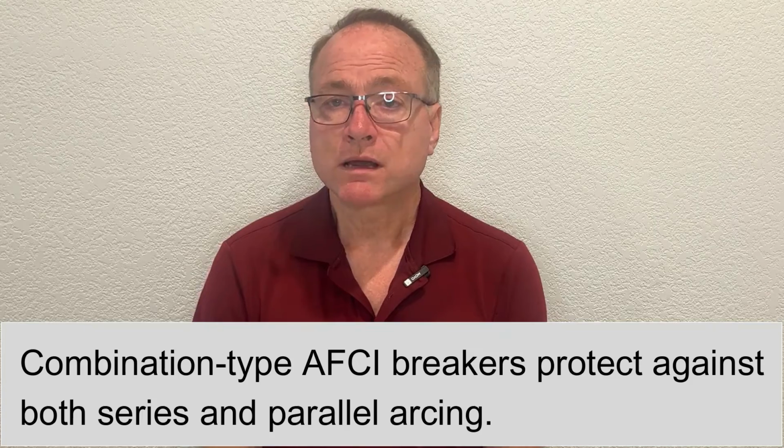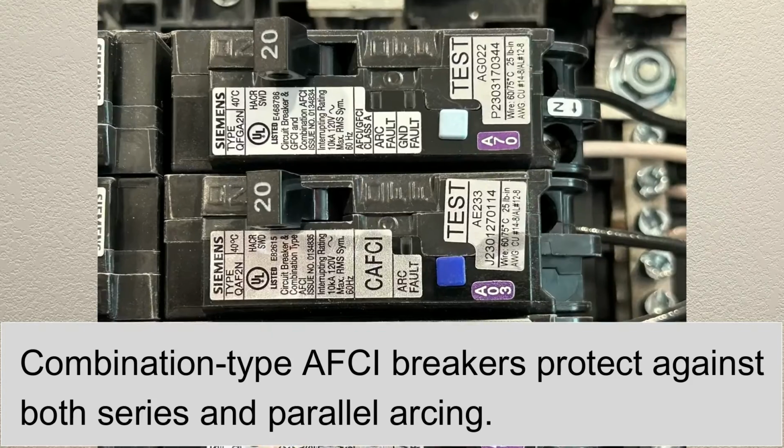When arc fault circuit interrupters first came out in 1999, they only had AFCIs that protected against parallel arcing. But now they also protect against series arcing. So they're much more effective at preventing electrical fires. The type of AFCIs that prevent both parallel and series arcing are called combination type AFCIs.